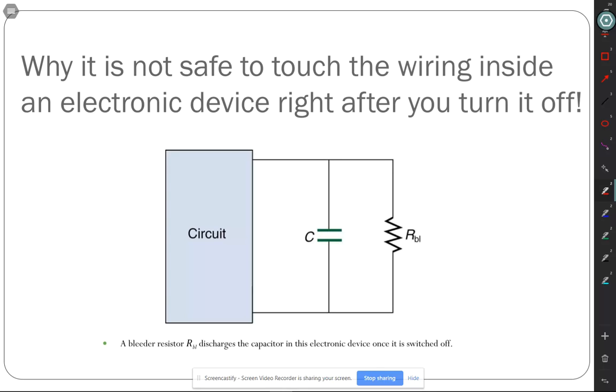When you go a high enough voltage, the current will be high enough to be dangerous. Hence the signs that say, warning high voltage. And all the smart Alecs say, it's not the voltage that kills you, it's the current. Yes, but if it's high voltage, it's going to be able to put a large current through you. That's why it has warning high voltage. So voltage is an important factor. Now, if you have alternating current, things change a little bit, so we won't deal with that. Ohm's law still applies in alternating current, as we'll learn soon, but it's a little bit different in the way the body responds. Really high frequencies, it won't penetrate your body type of thing.